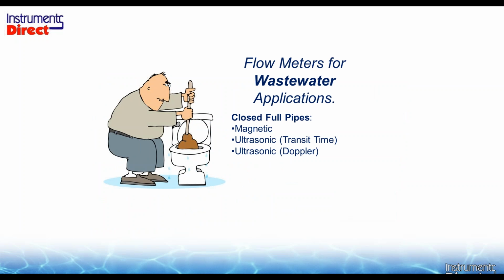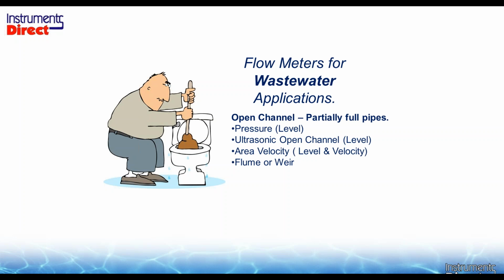The most popular category, the first category, would be a closed full pipe, traditionally pressurized. You can use different types of metering now because you're going to monitor a volumetric flow. So you would use a magnetic flow meter or an ultrasonic transit time flow meter or an ultrasonic Doppler type technology. And the other application that you're going to use for water and wastewater applications are pipes that are gravity fed, or traditionally partially filled pipes.